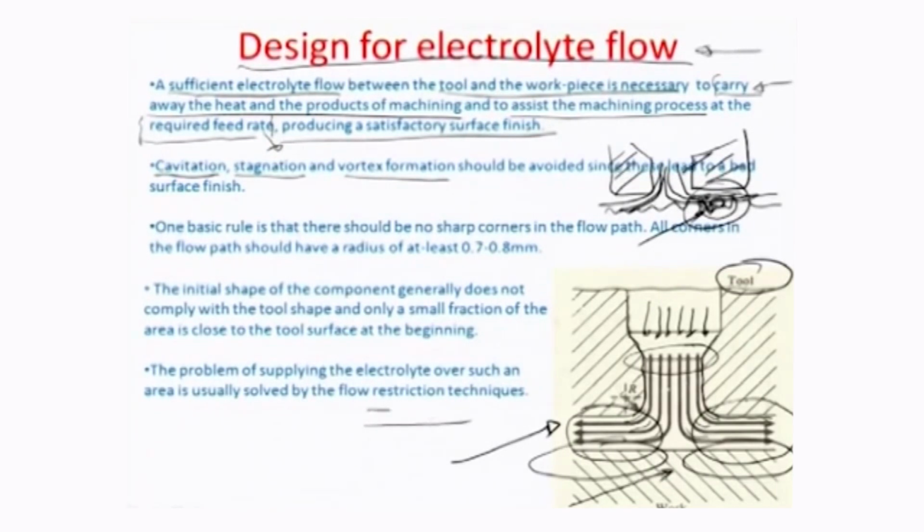Let us say this is the laminarity of the flow at this particular place, okay, and there is a big gap here. So, what would happen is if the flow goes inside, the flow would start to rotate in this particular region without being affected, even though the flow which is on the top of it is flowing in a streamlined and nice manner. So, these are the formation of local vortices or whirlpools.